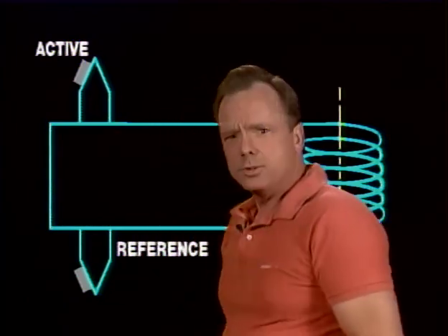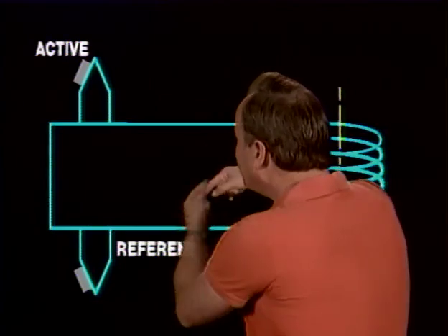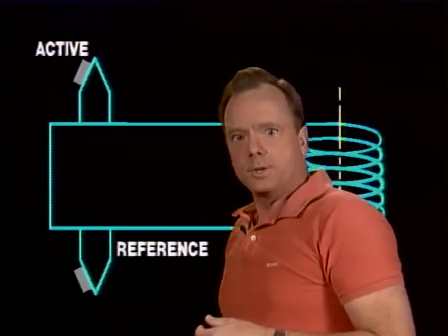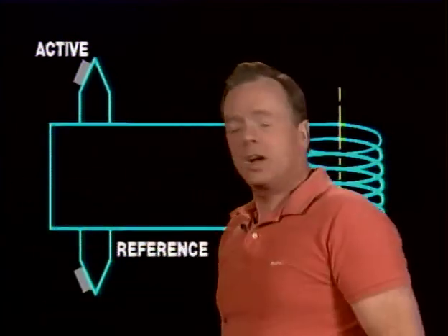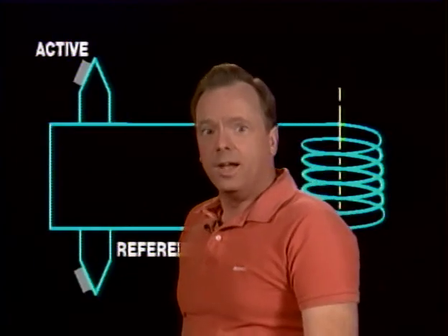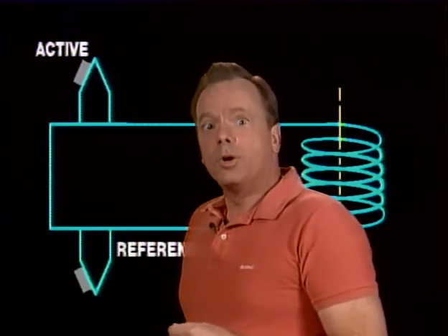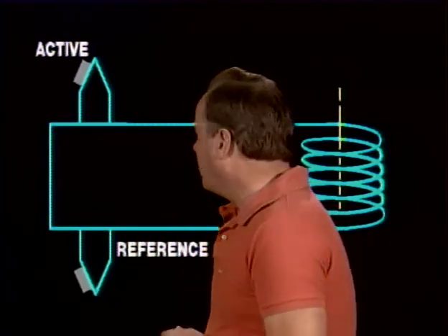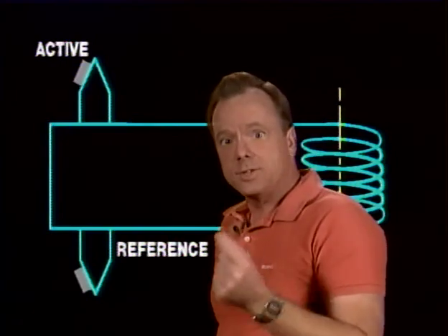Now they're going to say, all right, super mechanic, let's assume you get the leads crossed on a thermocouple system. Let's assume you just get them crossed at installation. What's going to happen? Well, if you hook them up backwards, get them crossed, the cylinder temperature gauge would move off scale on the zero side of the meter. It's just trying to read the other direction, that's all. And that tells you then you have the leads crossed, and that's what they're going to ask you about this on the test. Now, where do you normally put the thermocouple for a cylinder temperature system? And the answer is on the hottest cylinder, because you want to measure the worst case situation.